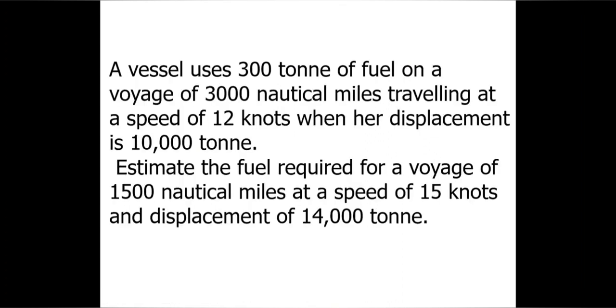A vessel uses 300 tons of fuel on a voyage of 3000 nautical miles traveling at a speed of 12 knots, when her displacement is 10,000 tons. Estimate the fuel required for a voyage of 1500 nautical miles at a speed of 15 knots and displacement of 14,000 tons. You can do this. We have to find how much fuel is needed for the voyage.